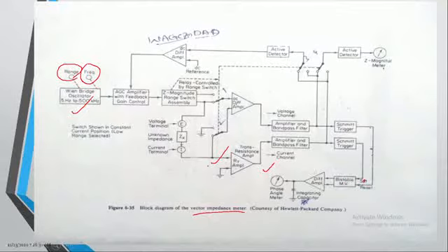And here we have the phase sensitive detector, the PSD. There are digital and analog phase sensitive detectors, but here we use the digital phase detector to calculate the phase angle between the voltage and the current, to determine whether the unknown component is a capacitor or an inductor.